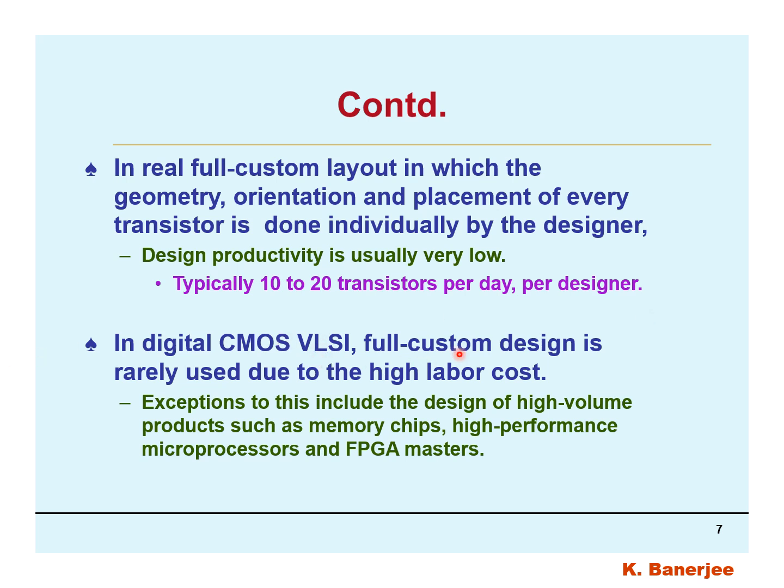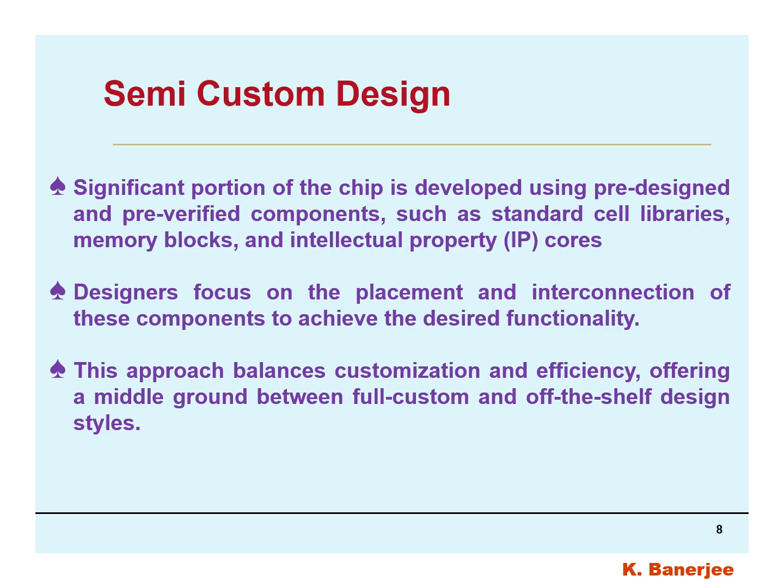In digital CMOS VLSI, full custom design is rarely used due to high labor cost. Obviously, everywhere there will be exceptions, and exceptions to this include the design of high volume products such as memory chips, high performance microprocessor, and FPGA masters, etc. So this is all about the full custom design. Let me discuss the semi-custom design, the next one.